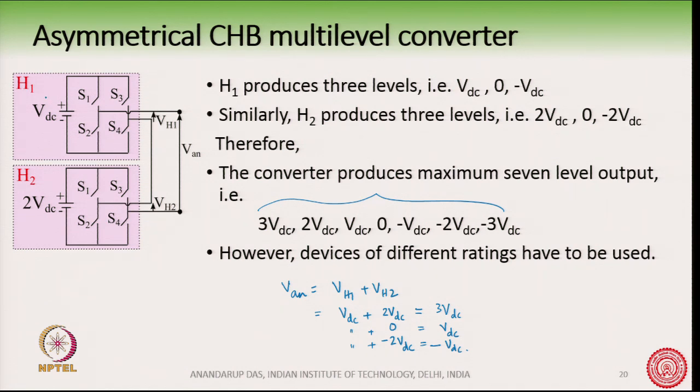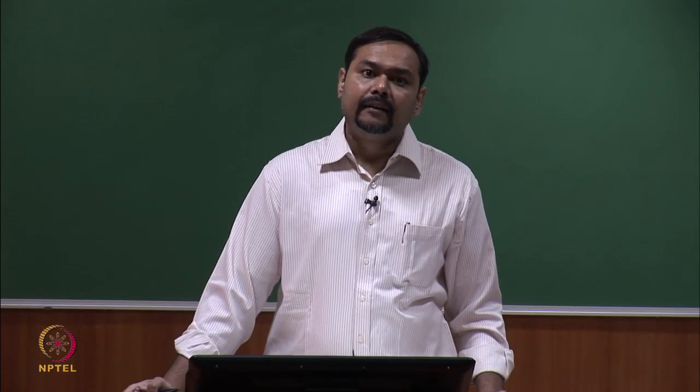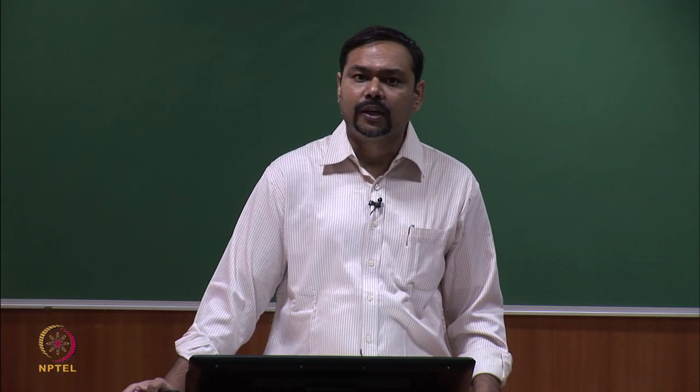For H1 we will need devices of voltage rating VDC, and for H2 we need devices of double the voltage rating. So, we lose the modularity, we lose the repeatability, and we have to have 2 sets of cells available.